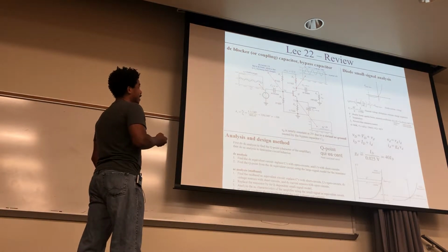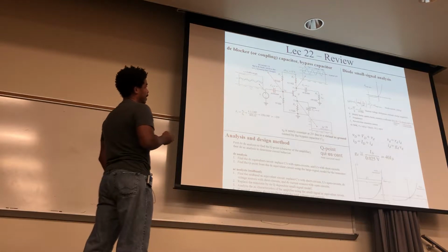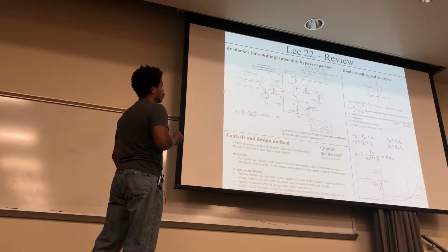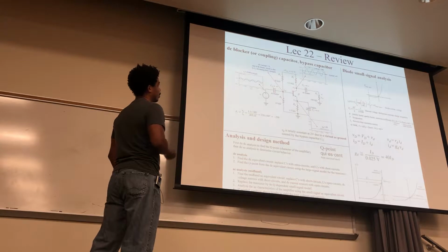What happens is that the capacitor becomes fully charged. After it's fully charged due to the DC voltage, then no more current is able to pass through. So you do have an AC signal of current that passes through, but not the DC. That's why the DC blocker corresponds to the current and not the voltage.